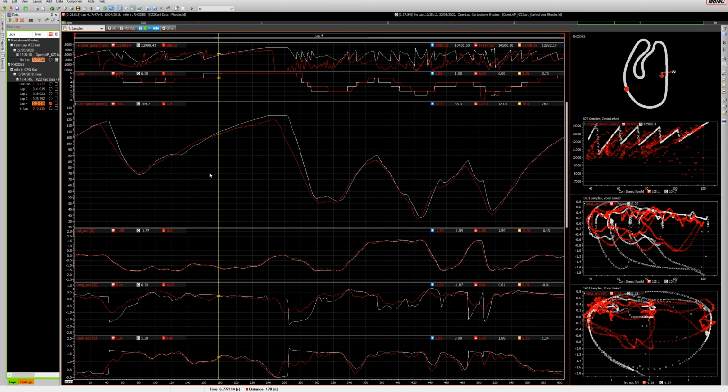Also, the drag that is induced when turning the steering wheel is not modeled in OpenLAP. And this is why, in the simulation, the kart can accelerate way more after turn 1 and is actually able to hit the speed limiter at the end of the straight. Again, the best correlation comes in terms of lateral acceleration, while there are more differences in the longitudinal acceleration channel.